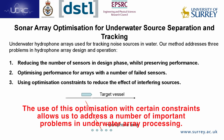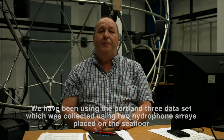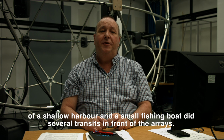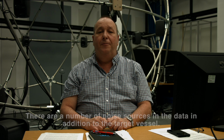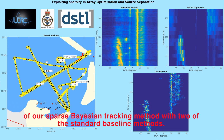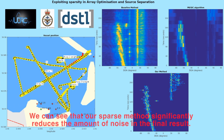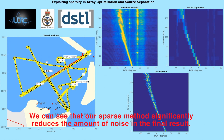The use of this optimization with certain constraints allows us to address a number of important problems in underwater array processing. In our work, we've been using the Portland 3 dataset, which was collected using 2 hydrophone arrays placed on the seafloor of a shallow harbour, and a small fishing boat performed several transits in front of the arrays. There are a number of noise sources in the data in addition to the target vessel. In our first demonstration, we compare the results of our sparse Bayesian tracking method with 2 of the standard baseline methods. We can see that our sparse method significantly reduces the amount of noise in the final result.